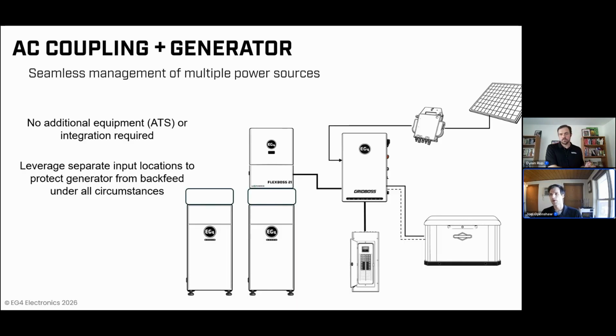Getting away from our hybrid inverters, I'd say there's legacy products where everything is built into one. You're kind of left with an either or, right? I've got a generator port, and I can either put AC coupled solar into it, or I could put my generator into it. You couldn't do both. Now that you have the GridBOSS, again, you have dedicated generator import, and you have 4 dedicated smart ports that can take the AC coupled solar or act as load shedding devices.